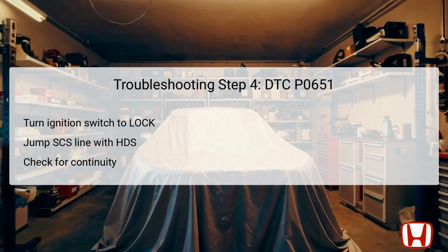The next step is to check for continuity between the test points and body ground individually, ensuring to follow all outlined test conditions. During this continuity check, you will examine the connections for both the APP sensor and the associated VCC terminals in the ECM connector.